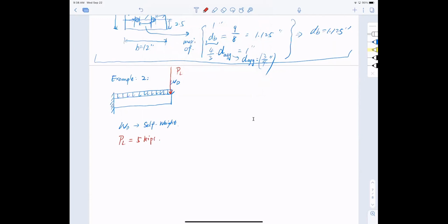And I'm doing a design with given section. So I say, look, the width of the section is fixed, and old friend 12-inch, 1 foot, and I have a height of 2 feet. These are my section properties. And my concrete is 4,000 psi concrete, old friend, and it's grade 60 rebar, which means 60 ksi yield strength.